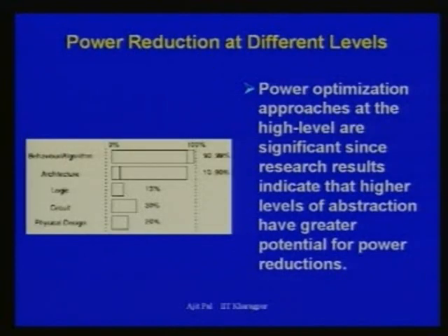So, you have to go through a number of steps, and we have to apply low power design methodology in each and every level of the design hierarchy, so that the power dissipation is minimized. And the impact of using low power design methodology at higher levels is more. For example, if you use low power design methodology at the behavioral or algorithmic level, there is scope for reducing the power dissipation by 90 to 99%.